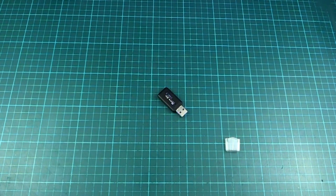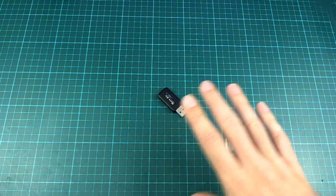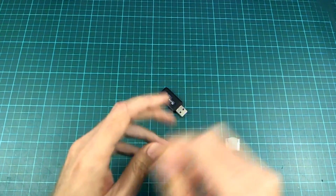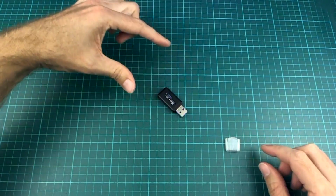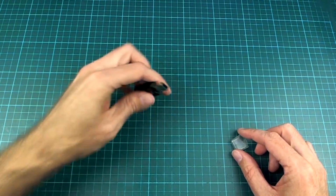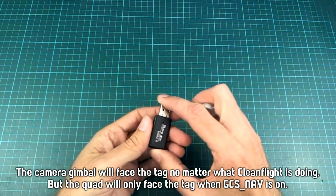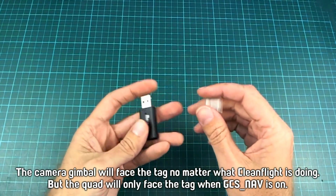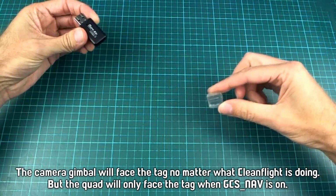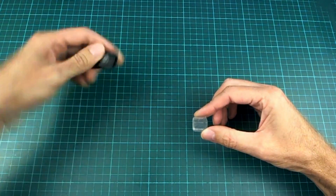In most of the modes for this follow me control, if you're putting it in the GCS nav mode, as we'll look at in a minute, the quad will orient itself to face the tag as well, so you shouldn't have it crossing over this 180 degree threshold very often. But if you're just flying fully manual mode, or in other modes like waypoint or return to home, you could quite often get the situation where the back end of the quad is pointing directly at the follow me tag, and then the camera will still do a lot of sudden moving around to get itself in the right place. But anyway, that is actually unavoidable unless you have a gimbal that can rotate in unlimited yaw.